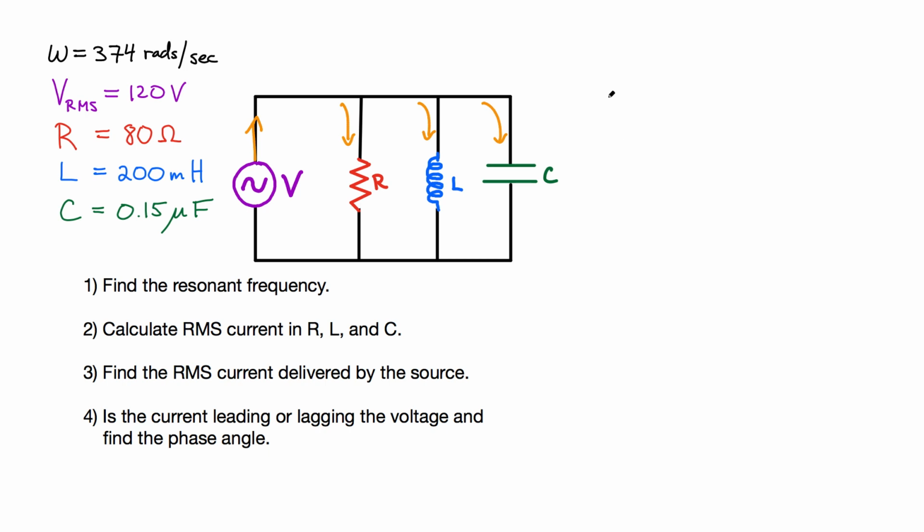So the first thing I would do here is simplify this circuit. Let's call this point A and point B. Basically I'll just redraw it and simplify it a little bit. First, instead of a resistor, let's represent it by a little box. I'm going to call this the impedance, Z, of a resistor. The impedance of the resistor is pretty straightforward. It's simply the value of the resistance.